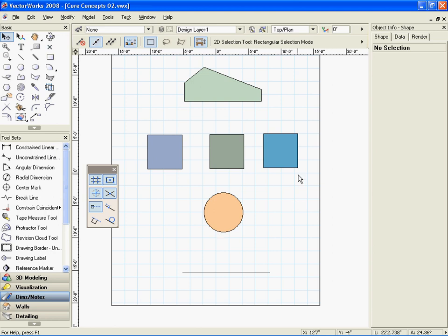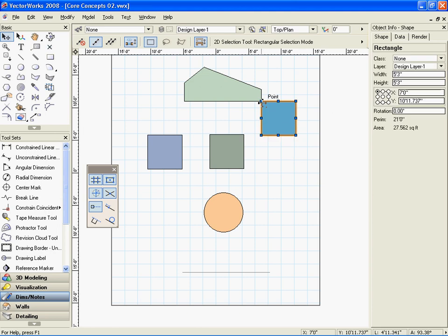Snap constraints are these on-screen smart cursor cues that indicate specific points and are another part of drawing accurately in Vectorworks. They are used to align objects, assist in the geometric construction of a drawing, and to find measurements and offsets. The key drawing constraints are typically always enabled, so they can be used without selecting buttons or typing keyboard shortcuts. By simply hovering over a point for a second, or by gesturing along the face of an object, you can find the required snap point or reference line.